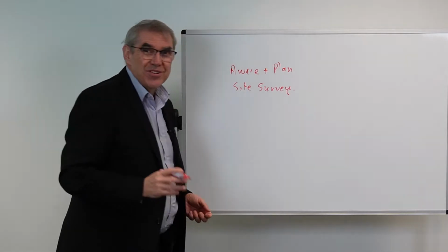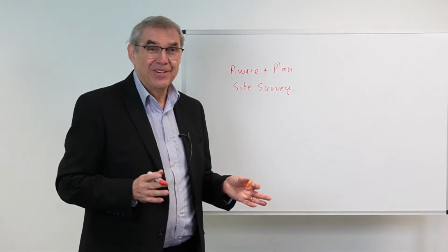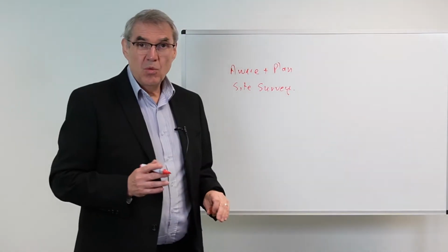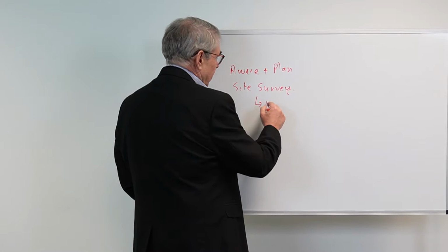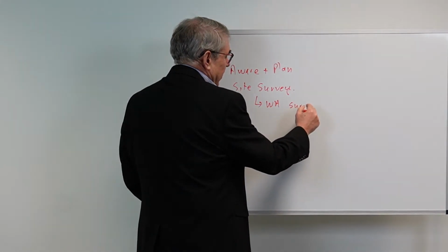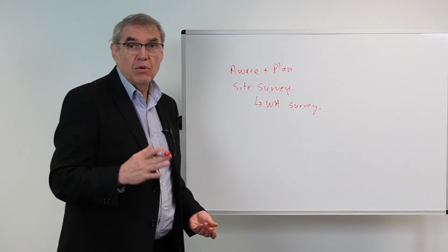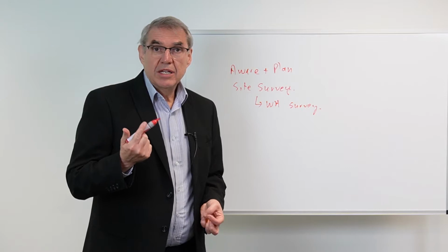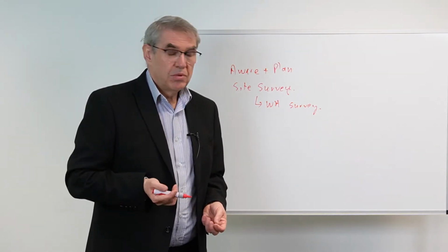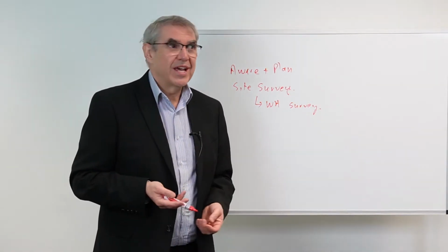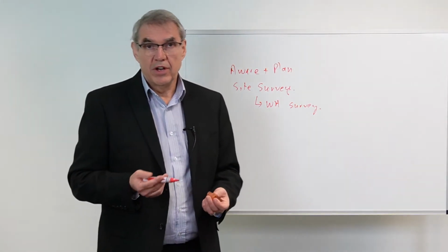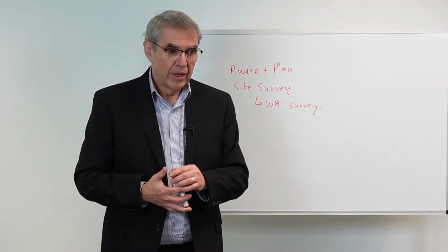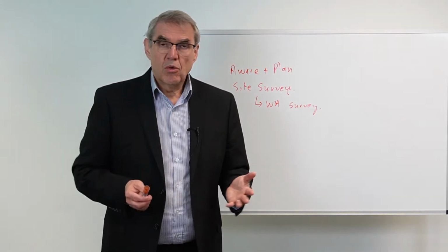Second, you need a site survey. If you've watched my videos before, you know we use a tool called PLATO. PLATO has got an energy audit module in there, but the site survey is a walk around. You go around, and you take pictures of all the energy consuming assets. So typically lights, heating, space conditioning, computers, machinery. You can do lifts, but what are you going to do with a lift? It'd be very unusual if you came up with energy saving measures for lifts, unless you really know what you're talking about. But anything like that, catering equipment, etc.